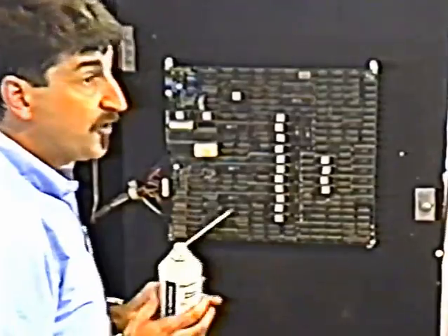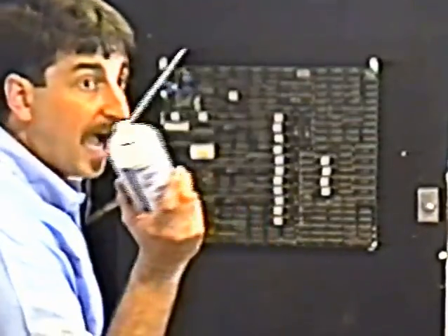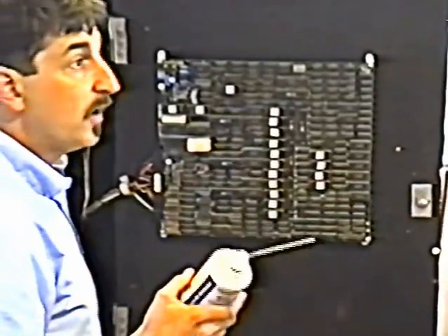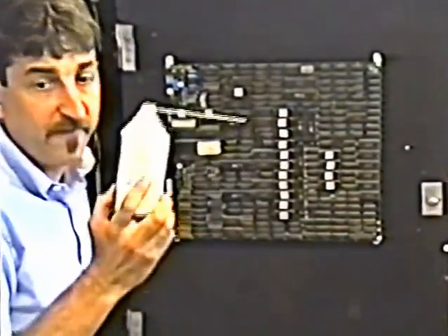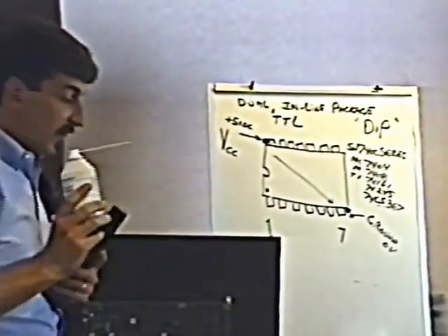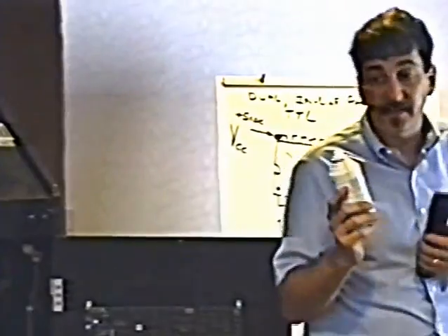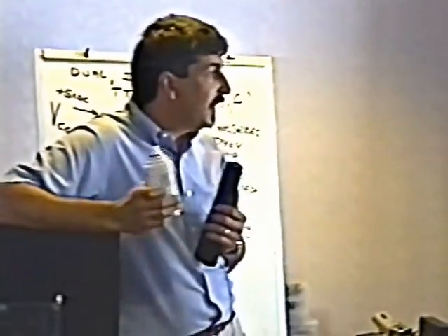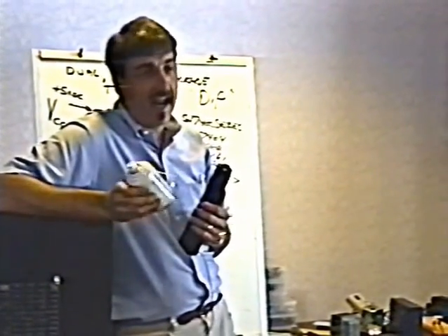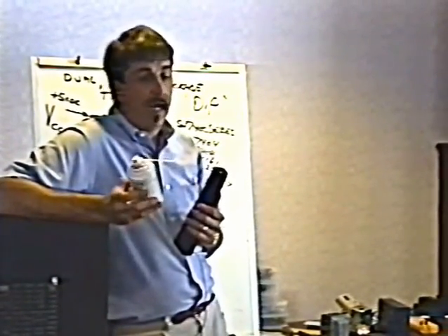Once you've located the chip, of course, this doesn't fix it. It only locates it for you. You know which chip is bad, same deal, then you order another chip. I have never failed to find a thermally intermittent problem with freeze mist. Never. I've gone through a couple of cans of it sometimes. It's always, of course, the last chip you hit. You can get it at any electronics store.